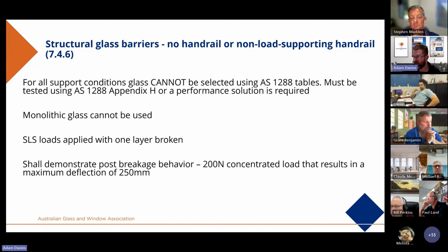Now, I do note in Appendix I there is no load duration given for that case, but it would be reasonable to assume the guidance from Appendix H could be used, which I believe is 10 minutes. Although it potentially is considered this load is not a medium-term load and would be a short-term load, which would move it down to 3 seconds. But currently it's not specified, but there will be some amendments made to cover that off.